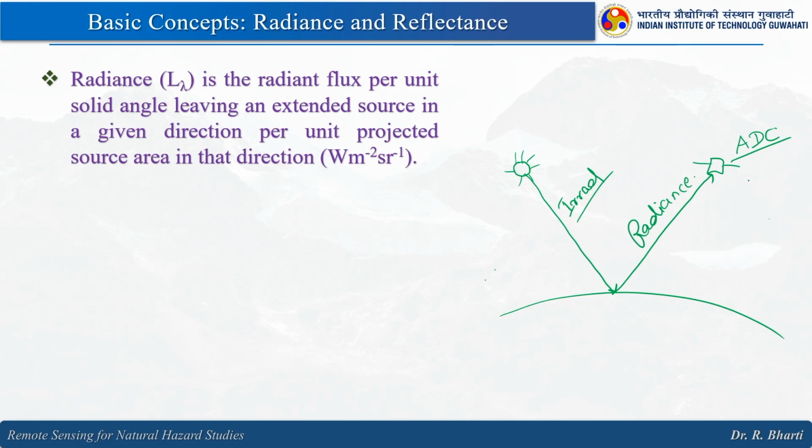So that will be a scaled number. So DN value is a scaled number, depending upon whether it is 2-bit, 4-bit, 6-bit or 8-bit, these numbers will be decided. If your sensor is 2-bit, you will have 2 to the power 2, right. If it is 8-bit, 2 to the power 8.